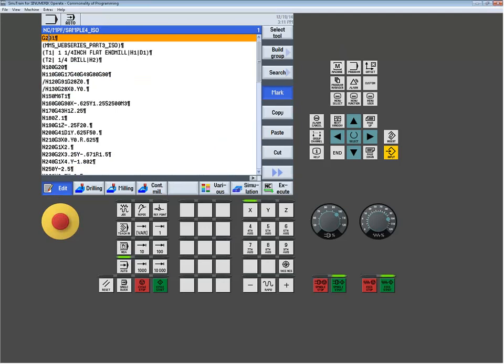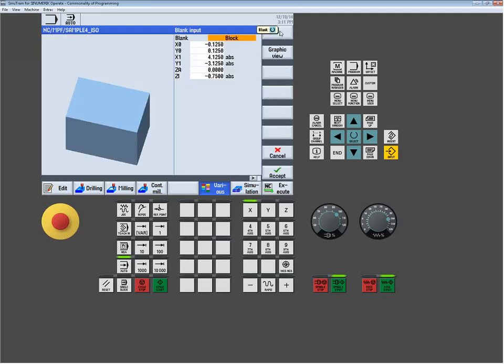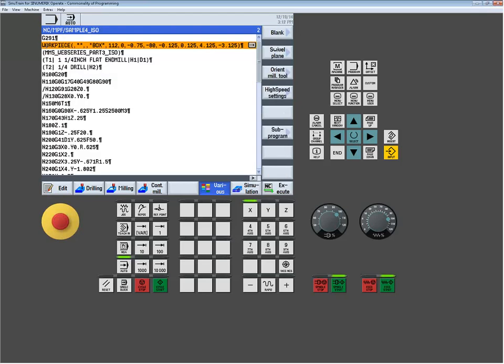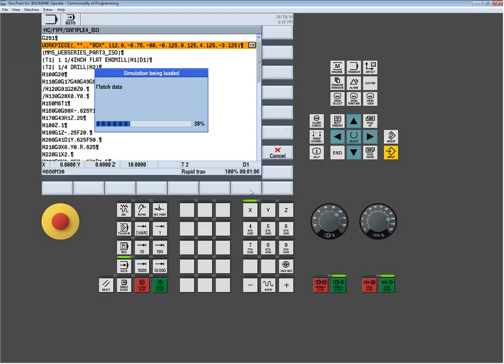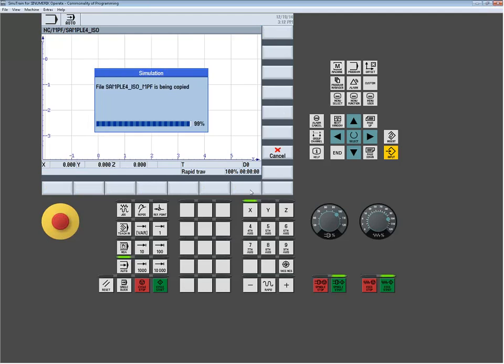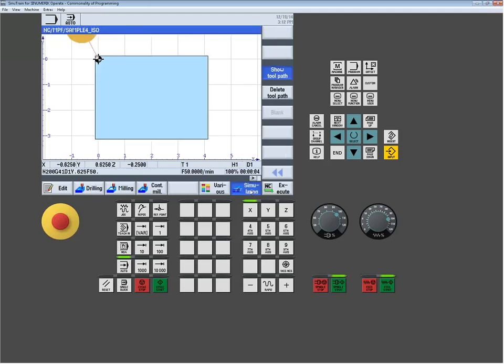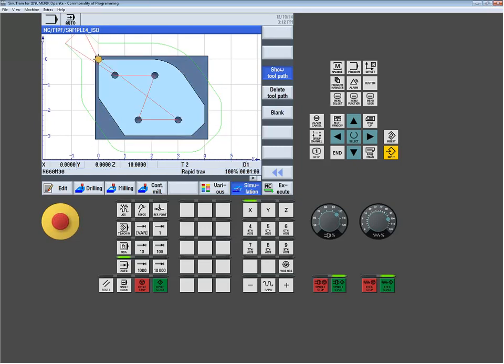Now, on the older systems prior to Operate, which is what we're running now, our current system, you had to be very careful, because the Siemens cycles had to be initiated outside of your 291 mode. Now we're allowing you to start to intermix some of the cycles. So here I can have the workpiece after my 291, and I can simulate it, and you're going to see it's still going to work. So here, blank comes up. It didn't give me any alarms. Before it would have given you an alarm. You had to solely do what could have been done in the ISO mode.